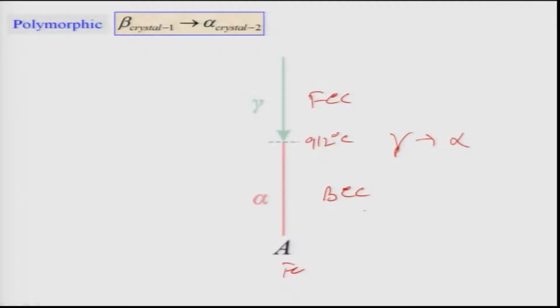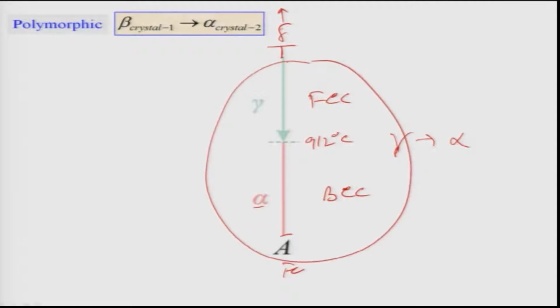Okay, now as you know, iron is a classic metal which undergoes polymorphic transformations, as I discussed in a few lectures back. Iron is a BCC structure at room temperature, which is known as alpha iron. At about 912 degrees Celsius, it transforms to gamma iron and becomes FCC structure. Again at a higher temperature, about 1492, it becomes delta, and then finally at 1539 degrees Celsius it melts to liquid. So the important transformation for our discussion is between gamma and alpha, and this is for pure iron when there is no carbon.